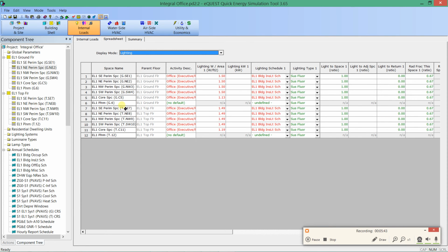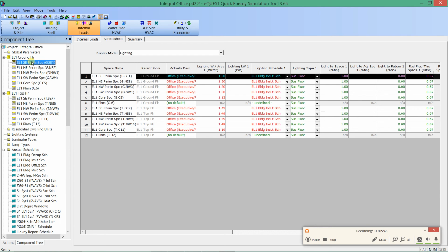They're actually libraries of schedules. We haven't looked at schedules. So for all the inputs themselves, once you leave the wizard mode, to really know what's the right square foot a person, you're going to need to find a reference if you don't already have a good sense for what square feet per person should be in, say, an auditorium compared with an office. But again, those tables are available through either California's Energy Code for free or older versions of ASHRAE 90.1. So when we come back, we're going to look at some of the inputs for the air systems, very similar to this, and we'll do an overview of schedules real quick.